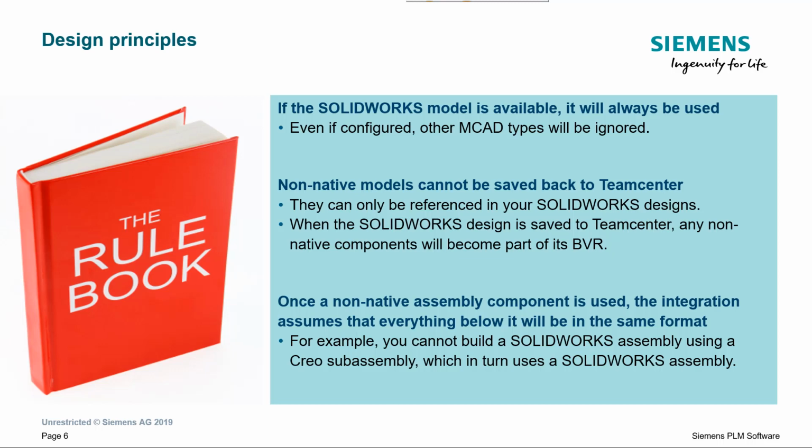Several rules are observed by the Teamcenter SolidWorks integration, when working with non-native design data. First, if a native SolidWorks model is found, it will always be used. Any other MCAD file, even if configured for reuse, will be ignored. Non-native models that are opened or inserted from Teamcenter cannot be saved back to Teamcenter as SolidWorks models. This preserves their identity and avoids duplication of designs under different CAD formats. Finally, nested reuse cannot be supported. Non-native assemblies of any depth may be inserted into SolidWorks parent assemblies, but they themselves must not contain any non-native children.